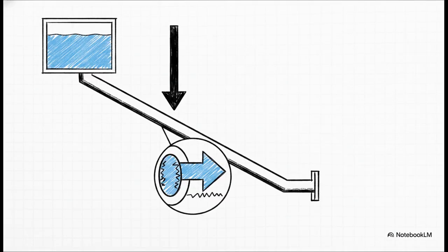If we run a theoretical test at a flow rate of 400 gallons per minute, we can plug our exact physical dimensions directly into our new simplified equation. We've got a pipe diameter of 4 inches, or exactly 0.1016 meters. Pushing 400 gallons a minute through that specific pipe gives the water velocity of 3.112 meters per second. We also have a helpful 4-foot gravity drop from the reservoir to the pump, which gives us some free pressure.